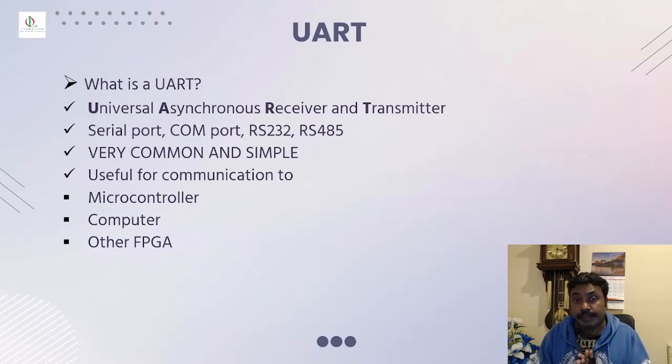And RS232, to transfer that data you want to transmit, can cover areas from 3 meters to 10 meters. So that's roughly the basic range. But if you want to send your data over long distances, then you have to think about going to RS485. That's covered for large distances.